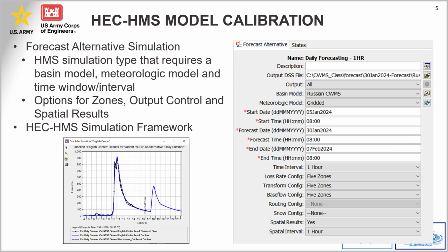This will save to the DSS file any updates just to what's been deemed as needed for this. We can equally do something in between this all and minimal, and it's a selected option. So when we choose selected, this cogwheel over here will illuminate, and it'll open an interface where we can just kind of do checkboxes throughout. It'll gray out what's deemed minimal, so we can't unselect the minimal, but then we can add selected data sets that we want. So in doing this, it's going to save a little bit on the compute time for saving the records, and then a little bit on the disk space, but this can add up over time if you want to take the time to do it on your initial.